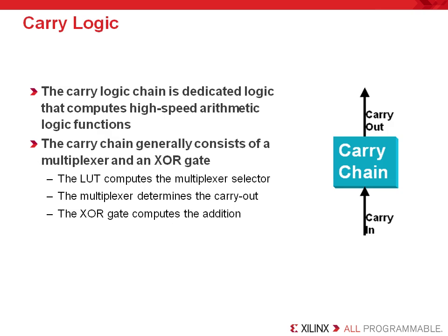The carry logic is a dedicated resource for propagating carry signals. This consists of a couple dedicated multiplexers, an XOR gate, as well as the LUT to implement a simple carry chain. Remember, this is dedicated, so it saves LUTs from being used to build this chain, and it is also very fast. The way to access this resource is by using an arithmetic operator in your HDL code, so the synthesis tool can infer the carry logic resource.